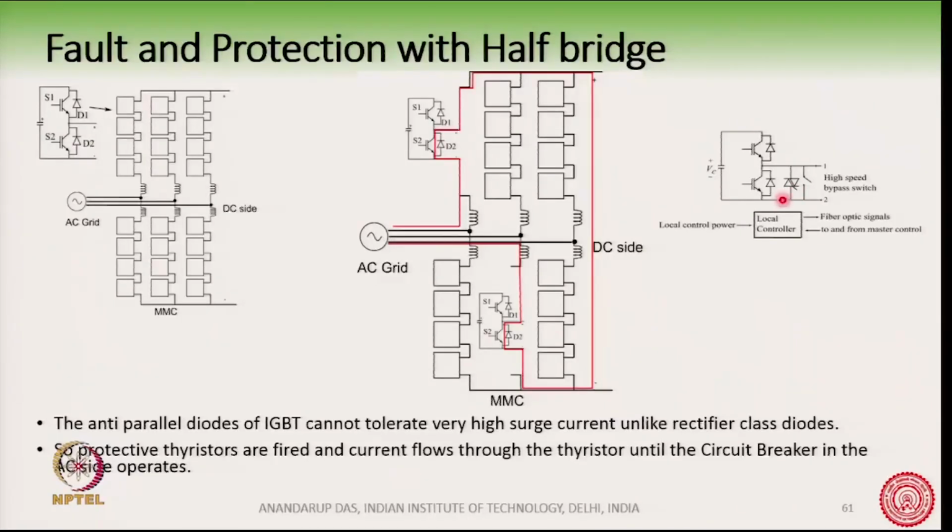Okay. And so, the current will now flow through the thyristor until the circuit breaker opens, that is about 60 to 100 milliseconds, the current will flow like this.